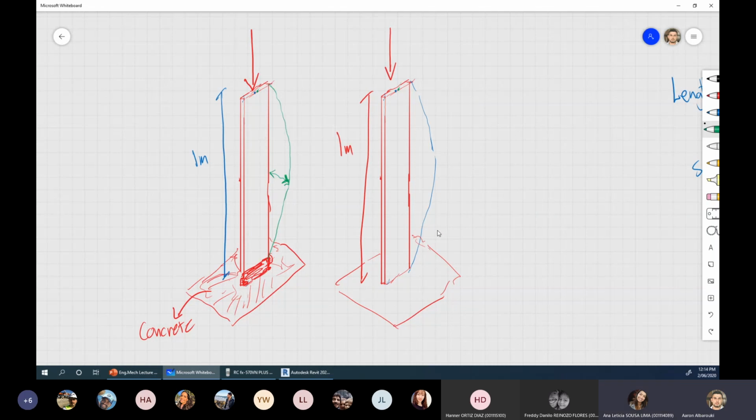Yeah. So, guys, let me tell you. Let me simplify it there for you. Do you agree with this? Let's delete that green line. What about if I tell you, and let's see if that will make sense. Rather than buckle that way, what will happen? Because it's cast in the concrete here, it's forced. It doesn't have the option here. It has to stay straight because it's sitting in the concrete. All of that has to stay straight for a little bit and then start buckling from here.